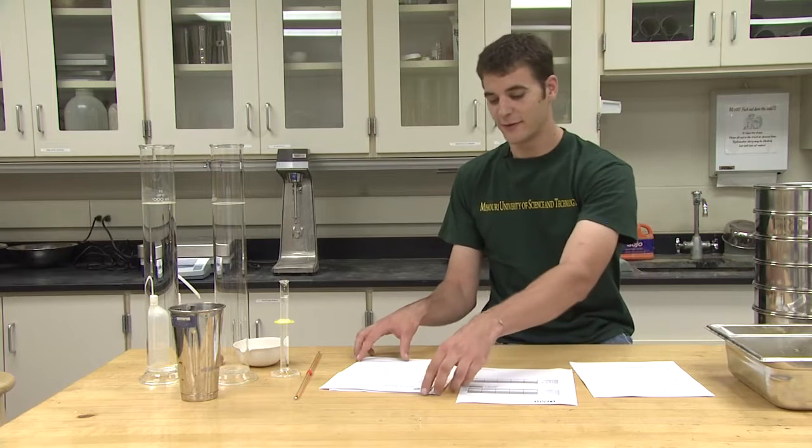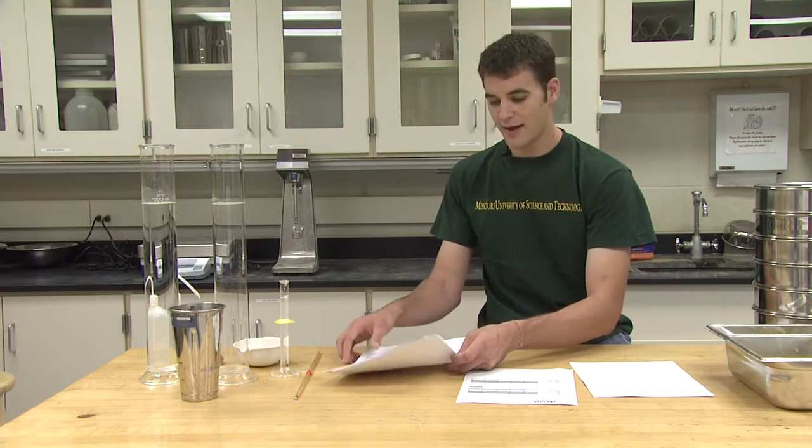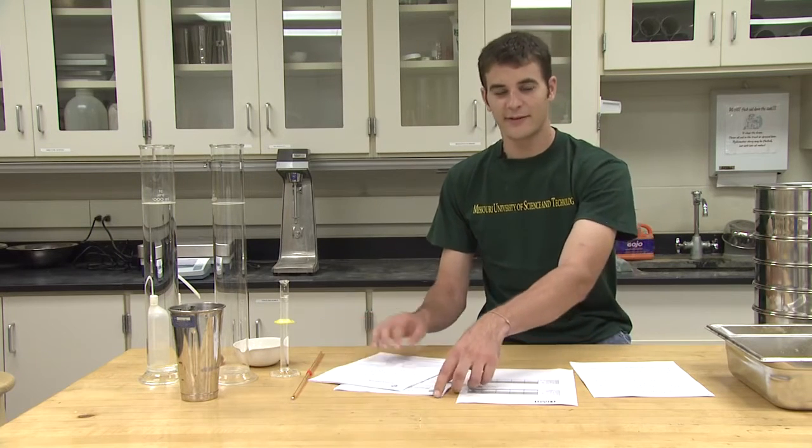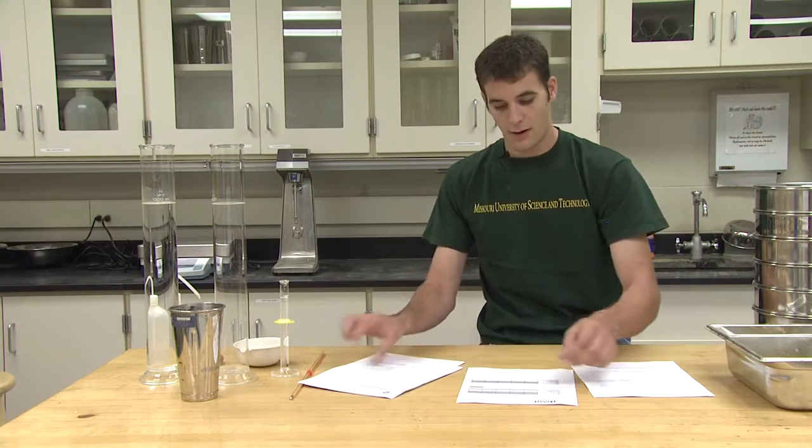The documents pertaining to today's lab can be found on Blackboard in PDF format. The particle size analysis is part of a combination lab handout entitled CE 215, Lab Number 3 and 4, Index Tests and Classification of Soils. In addition, ASTM standards of the two tests have been posted on Blackboard. ASTM C136 pertains to the sieve analysis of fine and coarse grain aggregates by the mechanical sieve. ASTM D422 pertains to the hydrometer test. Also available is a data sheet for today's lab.